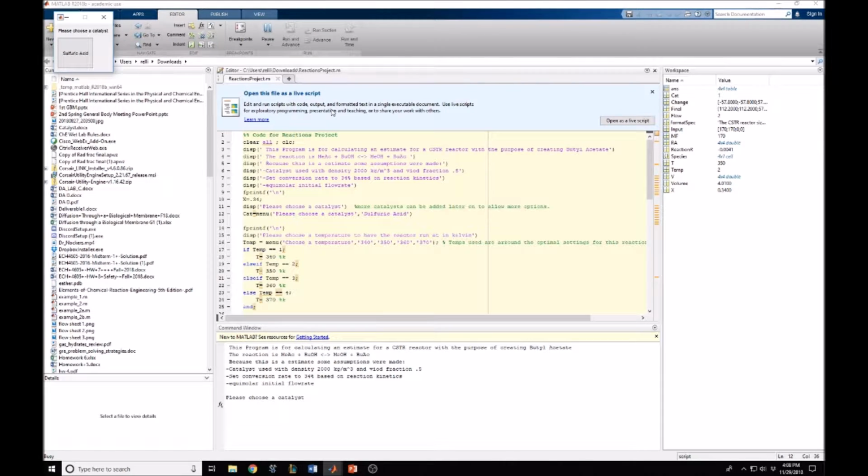All chemicals need to be stored and segregated in the approved area. Keep the containers in a cool, well-ventilated area, and keep them tightly closed and sealed until ready for use. And you should avoid all possible sources of ignition.